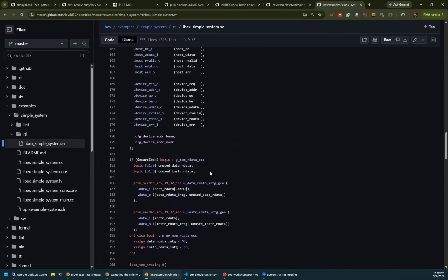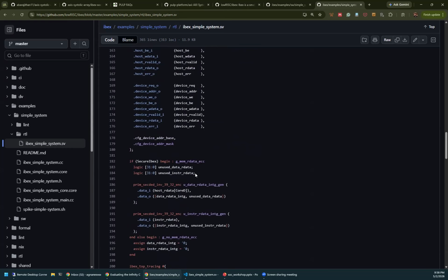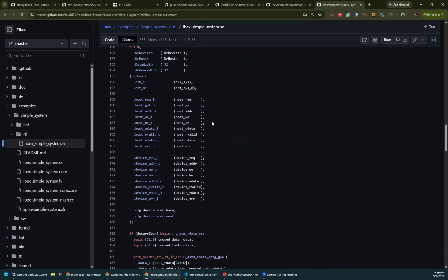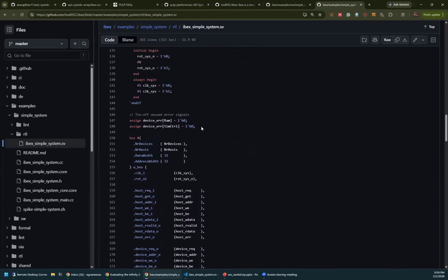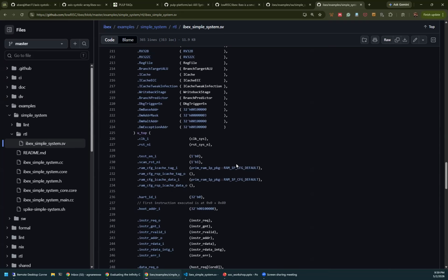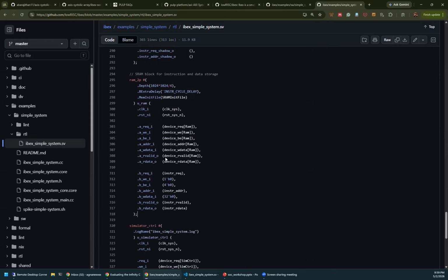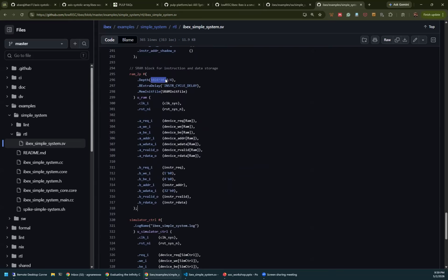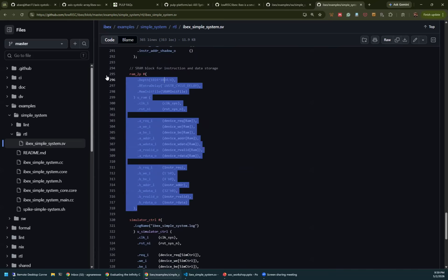Now we are going to put our own stuff in here, right? Our module has 4 master ports and 1 slave port, a slave port for the configuration, and 4 master ports that talk to the memory. I'm going to use the memory that they already have here, but I'm going to increase its depth, the size of the memory, so we can put matrices and stuff.